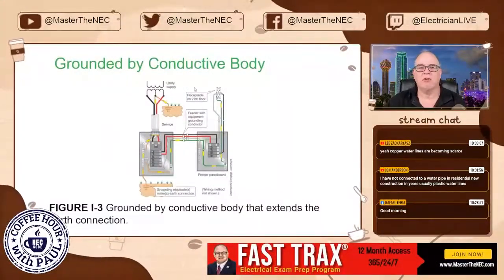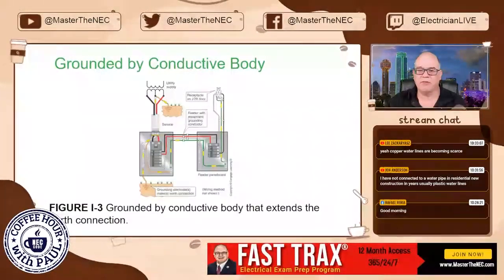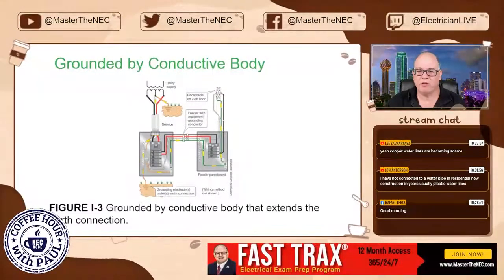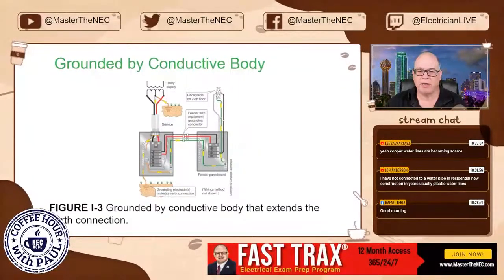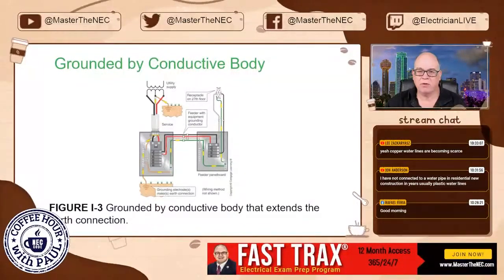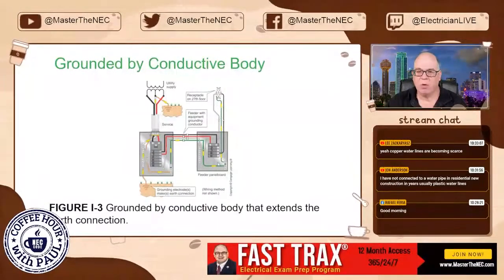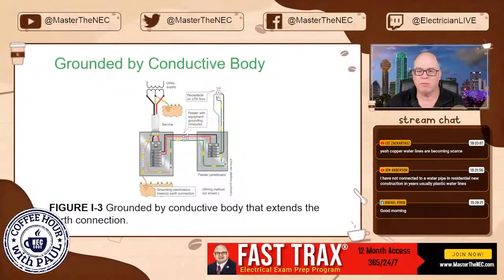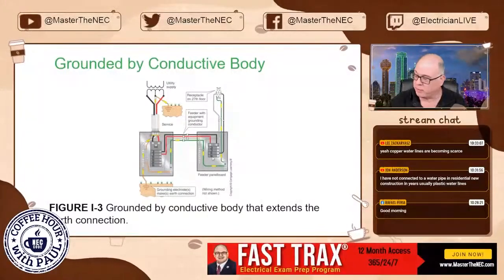All right, so here you go. So here you see that 27th floor extension. So here's your panel. Here's your remote distribution panel. People say, where's the main breaker? Because it doesn't have to be. It's in the same building. This is a remote distribution panel. It's protected right here on the line side, okay? So here we go right here. And the one thing to remember is your neutrals and grounds have to be separated on all remote distribution panels, okay? Whether it's in the same building or it's to a detached building, okay?